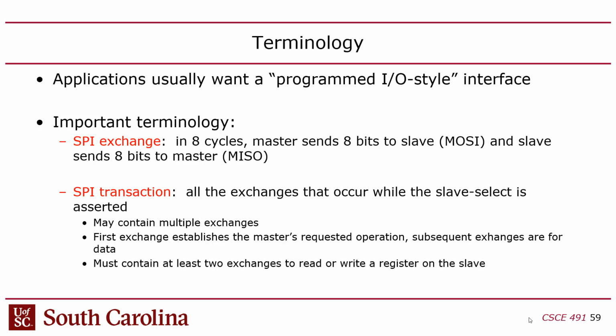It's pointless. Not only that, but the transaction part of this is actually an application layer protocol that's being built on top of the physical layer protocol of SPI. So SPI just defines the physical layer exchange mechanism, involving what slave select does and what CPOL and CPHA are.